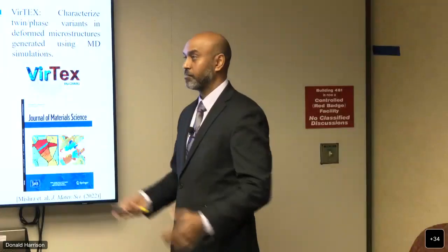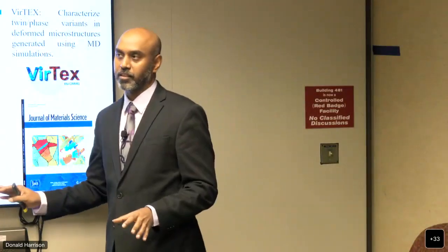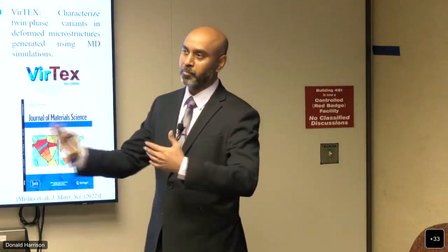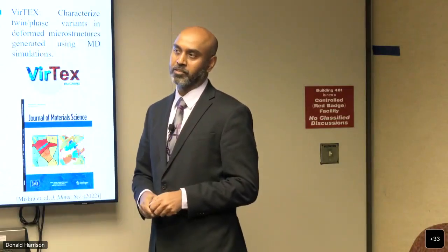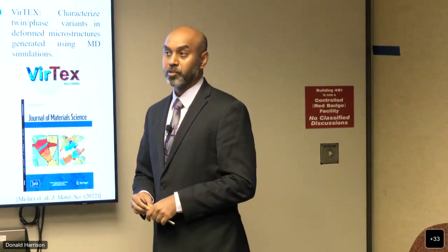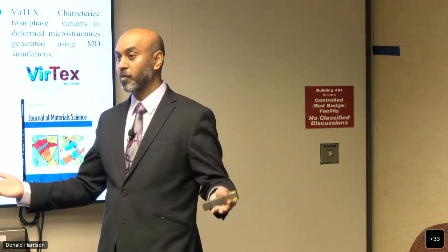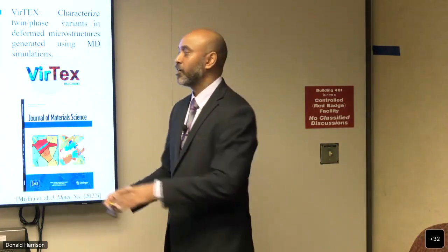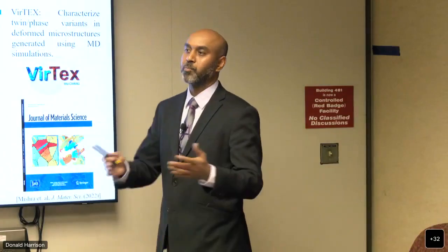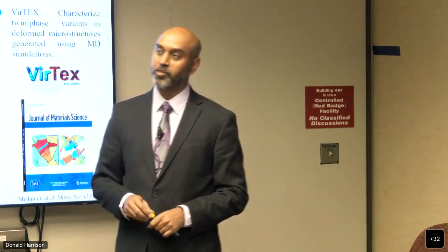So there's no correlation amongst neighboring grains? No, this is just randomly generated grains in that sense. And if you have a large number of grains, you have more or less all kinds of orientations incorporated in them. And the grain sizes also, we can impose any distribution that we would like to have as well. If you want a lot of small grains and a few large grains, we can do that. We didn't find the need to explore that avenue today. The focus is more on looking at the shock response.